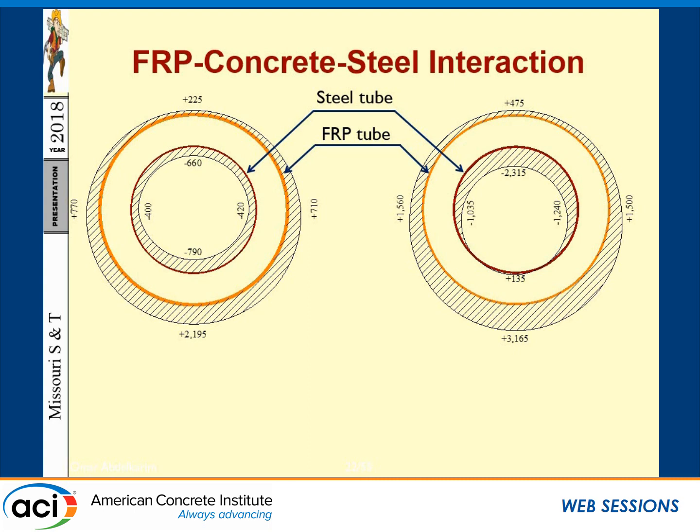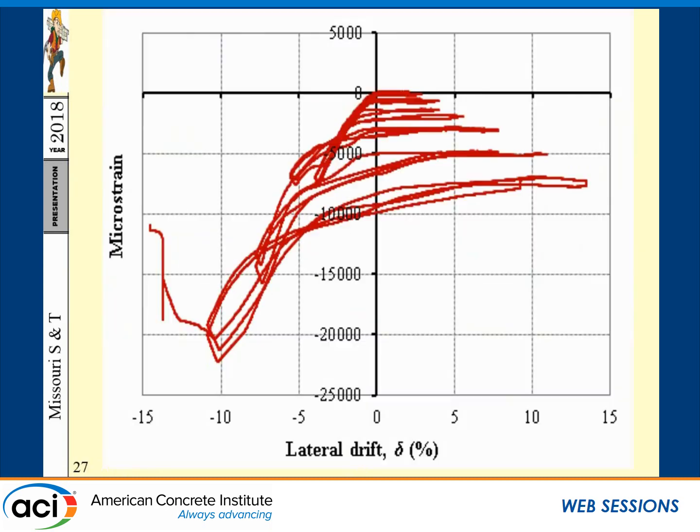So what we found, these are very much the same. The only difference is the steel. Whenever you have a thicker steel, the concrete finds it hard to propagate toward the steel, so it pushes versus the FRP and ruptures the FRP early. If the FRP is relatively thick compared to the steel, or stiffer than the steel, the concrete pushes versus the steel and the steel buckling happens quite early.